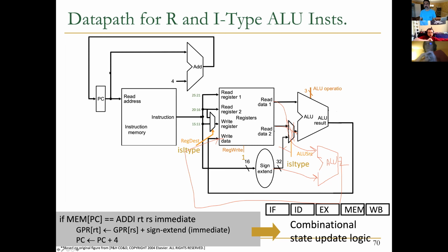All of these are perfect answers, actually. All of these are what I wanted to hear, right? So again, performance trade-off. If we add the second ALU, we may gain some efficiency in some specific design. Now we assume it's single cycle, but let's imagine that we have flexibility of doing things in parallel. But essentially, it affects cost, it affects time efficiency. As Noah said, it affects the space, right? So if you add an ALU, it means your board becomes larger, you need part of the board to implement two ALUs.